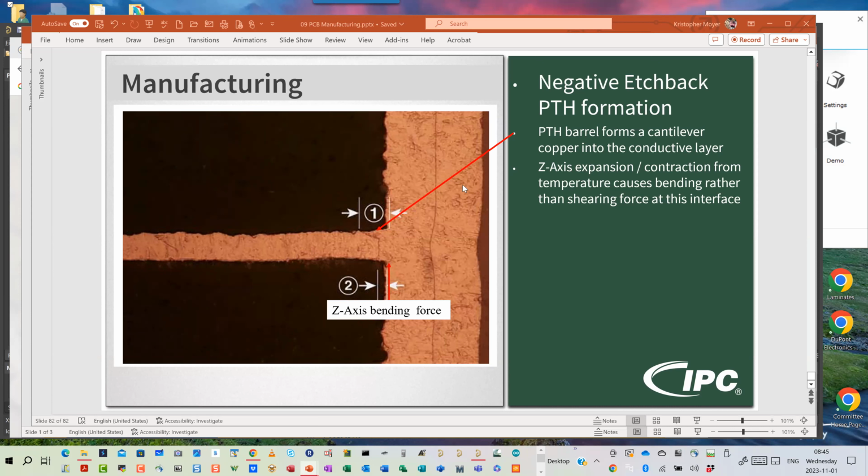The fabricators can manufacture it with or without etchback and get high yield, low scrap rate, regardless of whether or not you ask for etchback. We're specifically talking high performance reliability. Think military with extremely wide temperature ranges and products that have to work the first time every time, in the deserts or the Arctic or whatever the case is, or think high vibration: airframes, jet airliners, fighter jets, and so on. So we're talking performance reliability, not manufacturing reliability here.